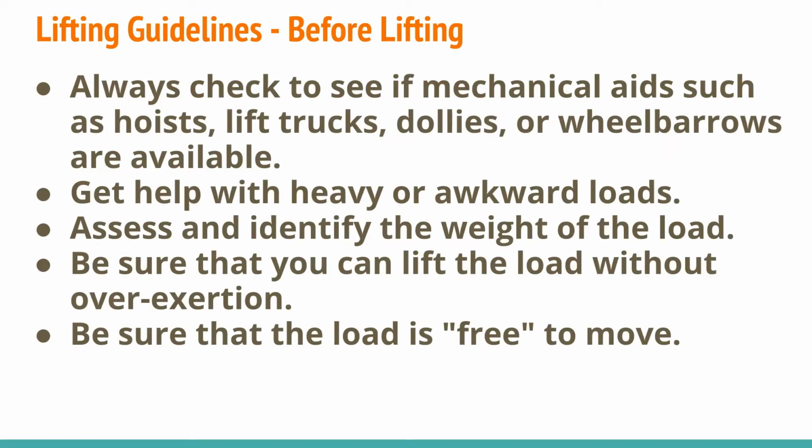In lifting, before you lift any heavy object of any kind, always check to see if mechanical aids such as hoists, lift trucks, dollies, or wheelbarrows are available. Get help as much as possible with heavy or awkward loads. Assess and identify the weight of the load. Be sure that you can lift the load without overexertion. Be sure that the load is free to move.